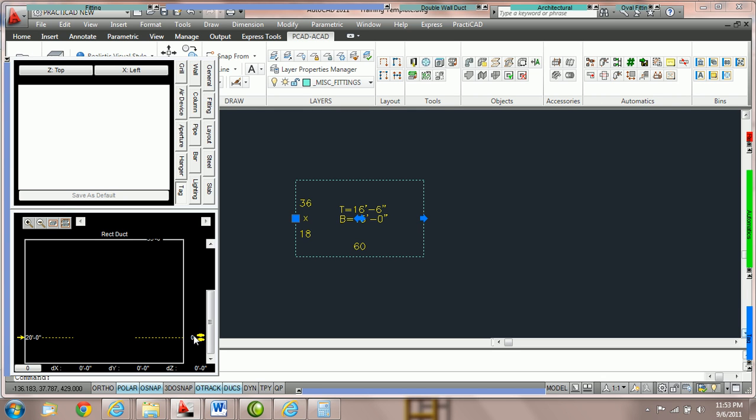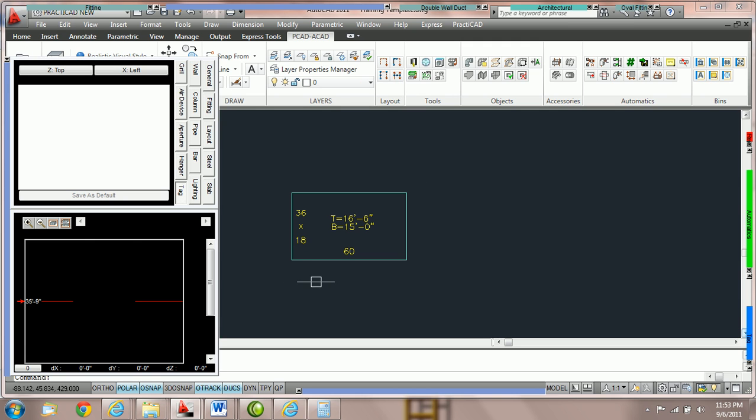So the first step on every drawing is actually to open up your drawing, find out what your new 0 is, or your new reference point, put it in as 0.0, and then set it to relative bottom to start. So let's continue to look at this. I'm going to use my elevation marks view to center from my highest point and my lowest point.